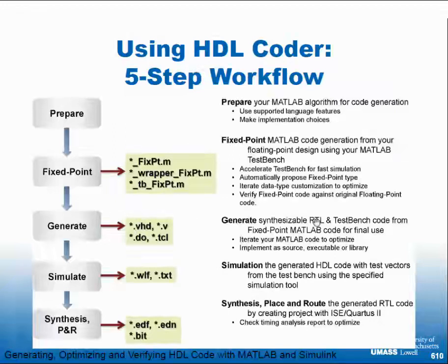Then you generate your RTL and the test bench from the tool. You run your simulation, which is uneventful, more than once. This is not a linear process, there's some iteration that goes on in all these steps. But you get to that point, you decide that everything's good, and then you go and synthesize your code, right? The actual FPGA design. So really, these three steps here are running in parallel with a development step and a verification step.